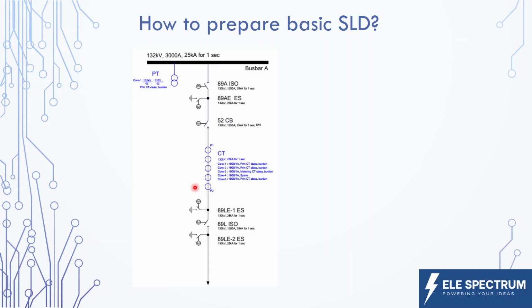Now, the next important topic is where this current transformer should be located. As this is a series element and it needs to detect the current which is flowing through the feeder, we have the possibility to place it in two ways. Either it could be placed before the circuit breaker at this location, and it could also be placed at this location as we have shown right now.